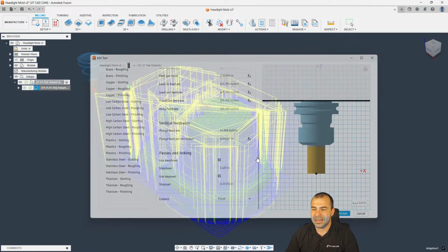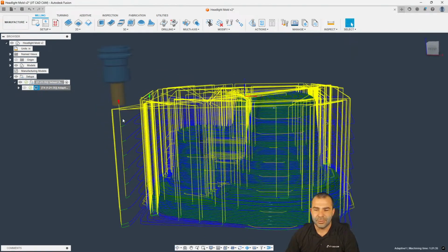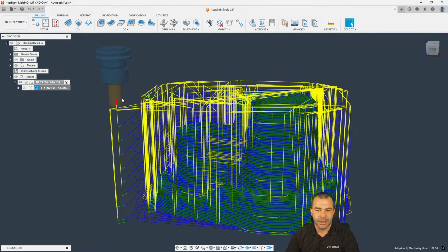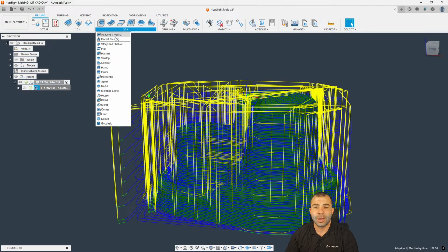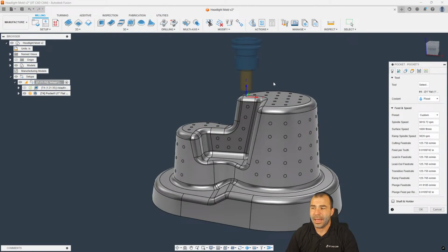But as you're going to see, again, we're not going to make any changes here. We're now doing our 1.1 depth of cut, always doing a 40% step over. Now that's going to require quite a bit of torque, which is going to require me to either slow down my feed rate or increase my spindle RPM, which I could be in danger of getting too high and getting out of my torque curve. Now, more commonly, this was a traditional approach. It still works well, obviously, on your thinner parts and things of that nature.